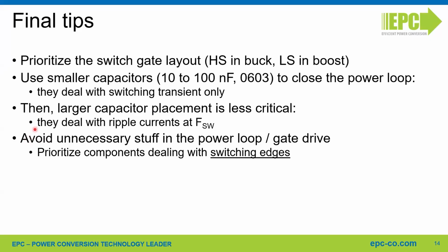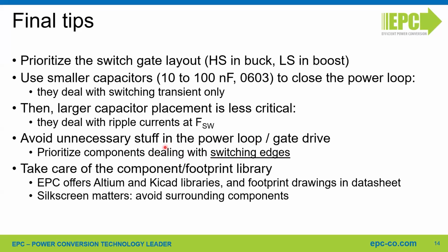As advice, I've seen a lot of components close to the gate of the FET that are working at low frequency or DC, and those components can be placed away from the gate, keeping only the critical components in the close vicinity of our devices. So gate resistors, those are dealing with the switching edges.